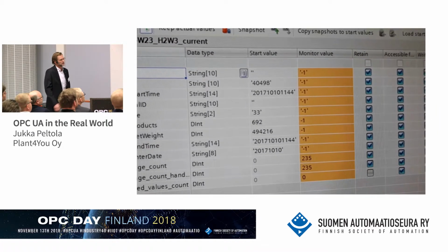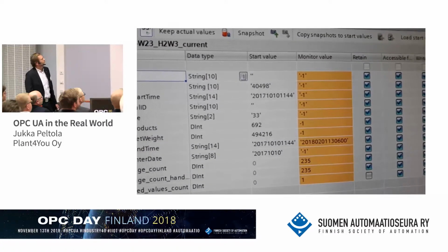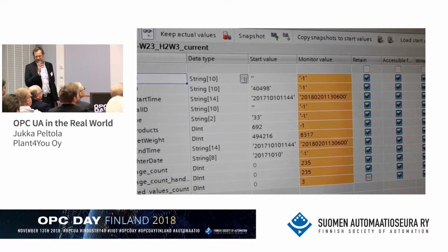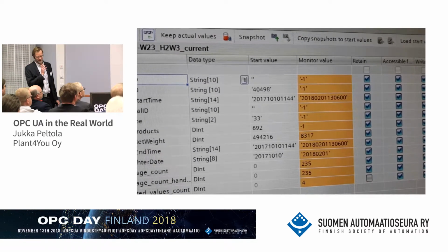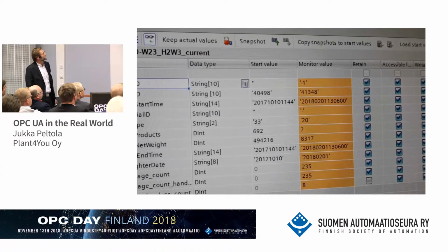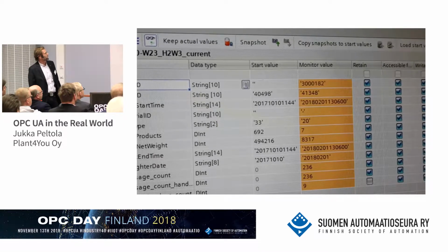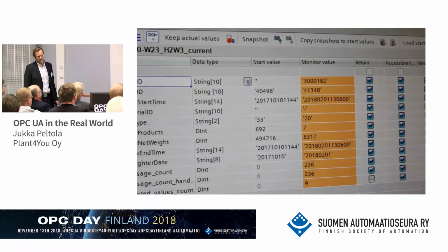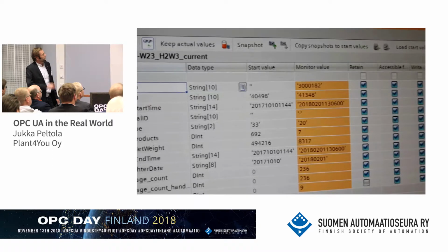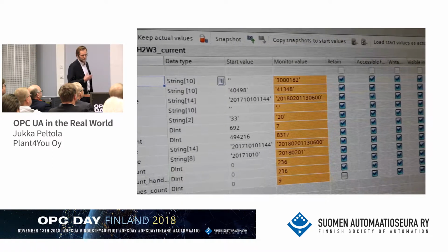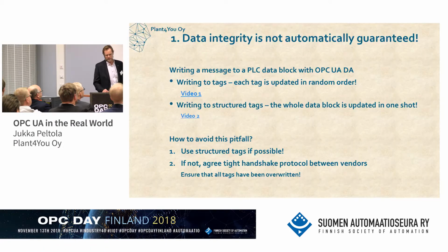-1 was the reset value. And you can see that it is quite slowly updating all. The client has written everything at once, but on the server side, you could see that it is updating very, very slowly. And that's why we had to do, in some cases, quite a strict handshake protocol, where the server is really checking that every pin is written before the data integrity was guaranteed.